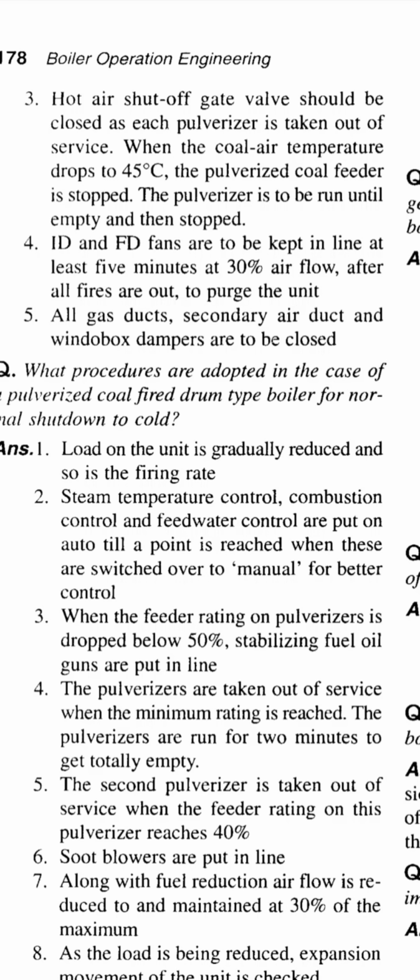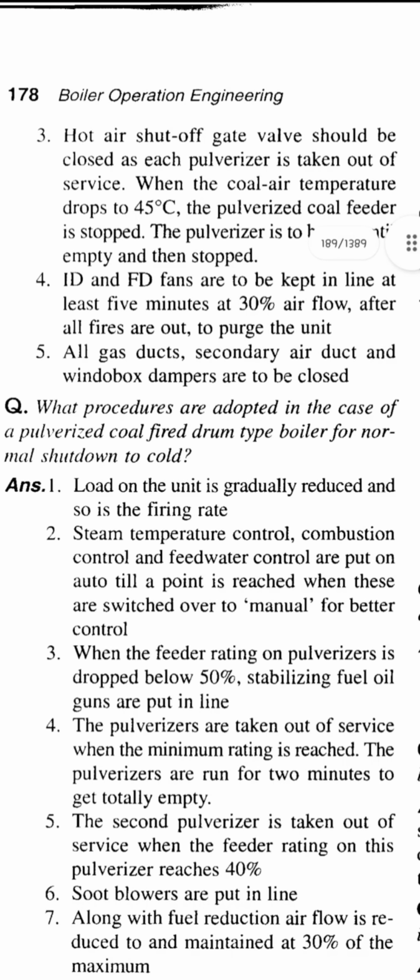Fourth one, ID and FD fans are to be kept in line at least 5 minutes at 30% of airflow after all fires are out to purge the unit. Fifth one, all gas ducts, secondary air duct and windbox dampers are to be closed.